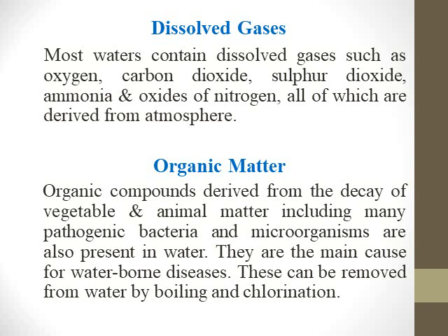The water which is fed inside the boiler should be free from all four different types of impurities. The first one is dissolved impurity, in the form of calcium, magnesium, and sodium bicarbonates, chlorides, and sulfates mainly, and traces of nitrates and nitrites.